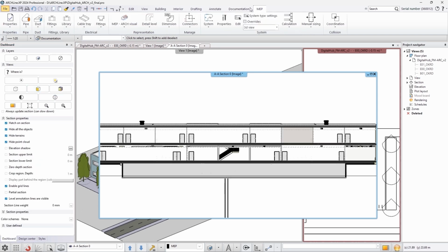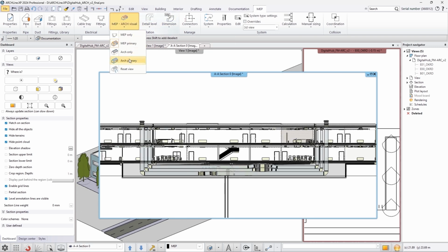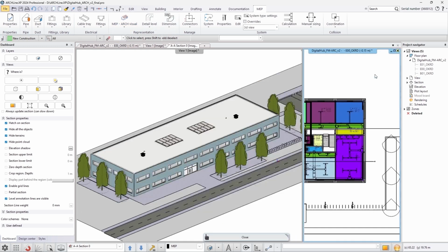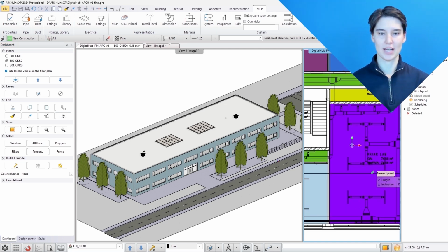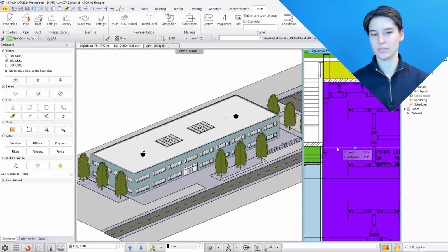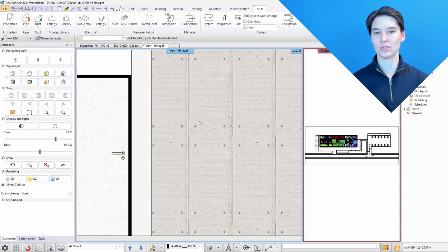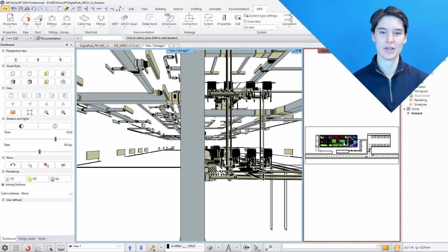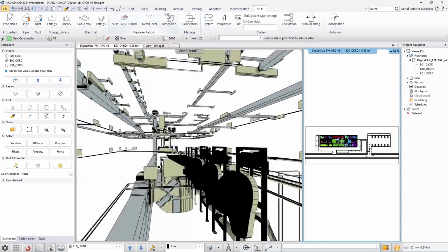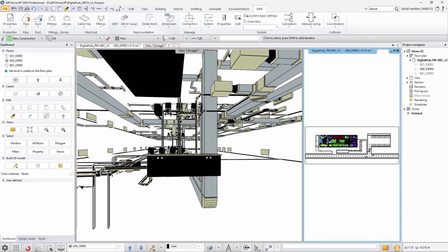It is a very important part of the process, as it lays the foundations for many construction-related plans, sections and elevations. It can also be used to create a detailed overview of the building. Additional notes can be added to the 3D BIM model to ensure all of the measurements are clear for each discipline. Elevations and sections can also be used to explain and detail the layouts for anyone who needs access to the information. Using the Walk tool, you can navigate through a model as if you were walking through it. To walk through the model, drag the eye marker in the direction in which you want to move.